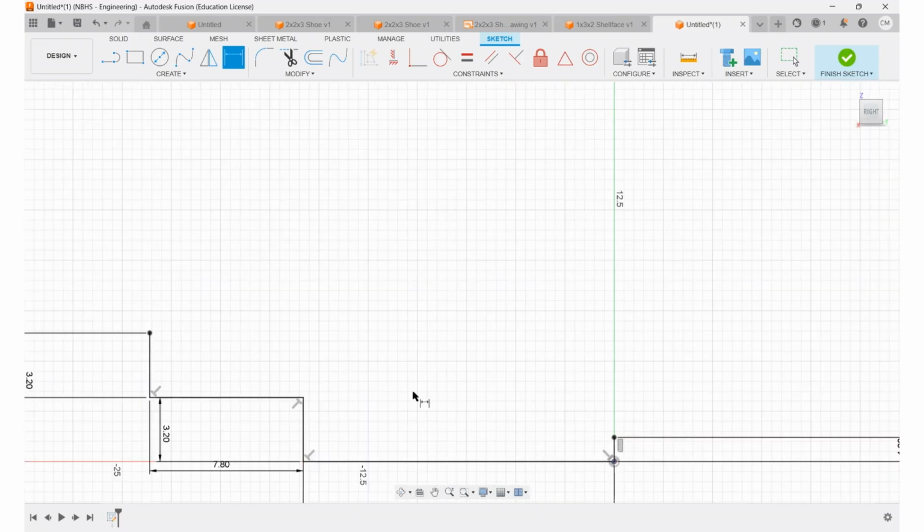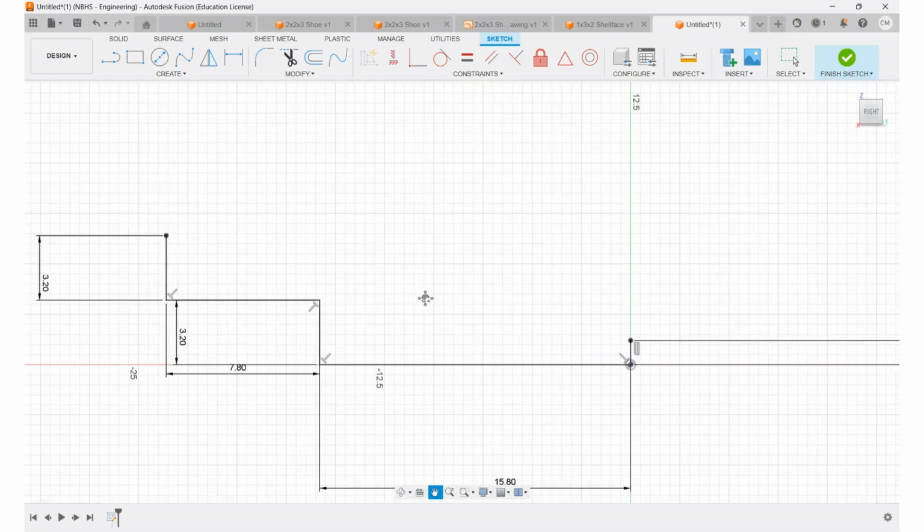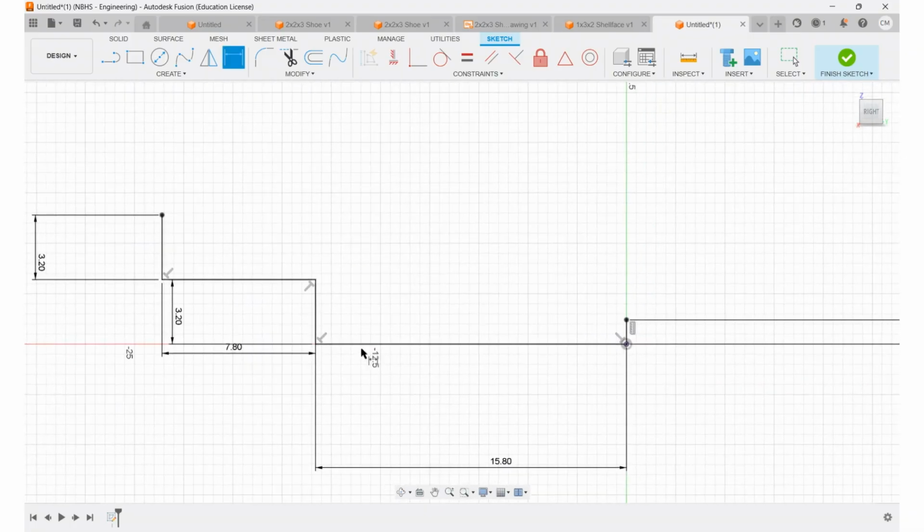All right, so you can see that I have a whole bunch of blacked out lines here, but I don't have that curvy profile. For that, I'm going to break out my spline tool. Now, the secret to a spline tool is you can use it to do things like trace, or you can make kind of complex little curves. Now, if you're going to do complex curves, fewer spline points are better. Okay, so I'm just going to have the 2 endpoints and 1 in the middle.